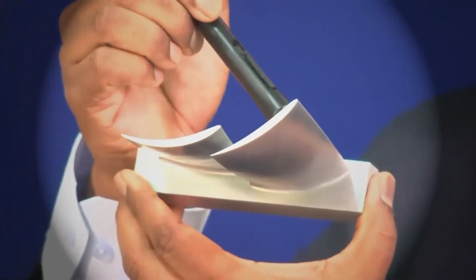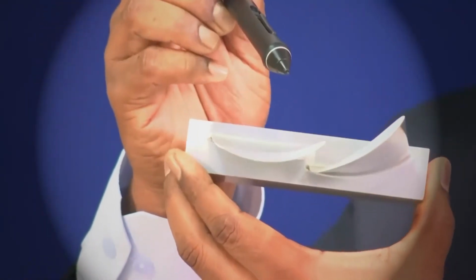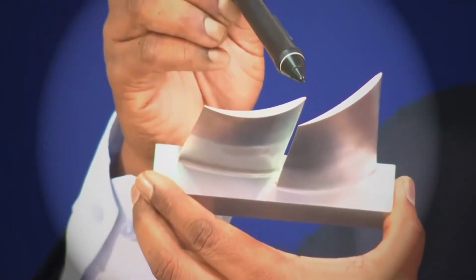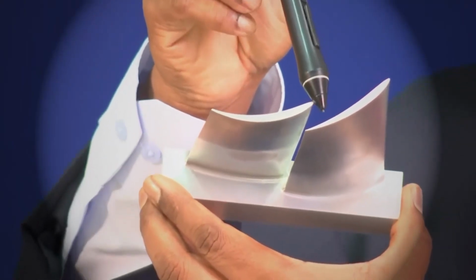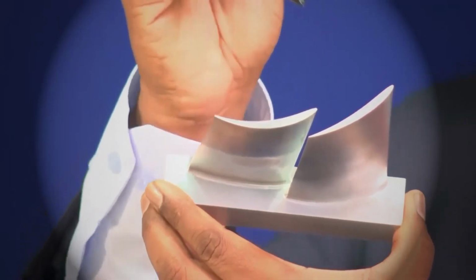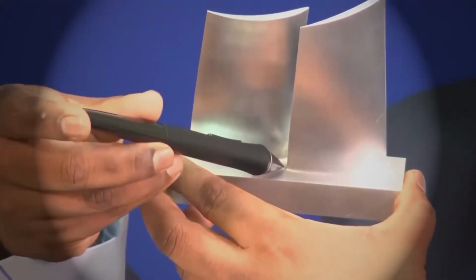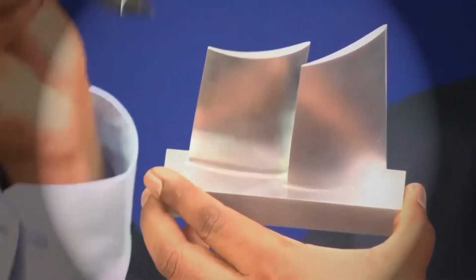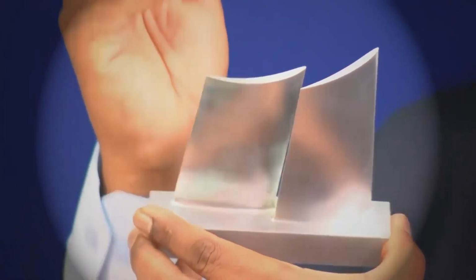This aerofoil has been stacked about the CG, and if you look carefully, our axial overlap is varying. Near the hub region, my axial overlap is 0, and here it is 3%.